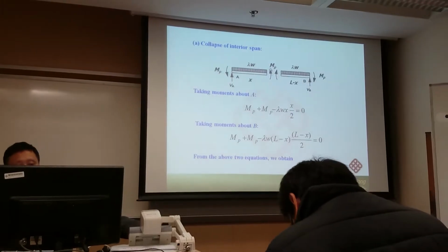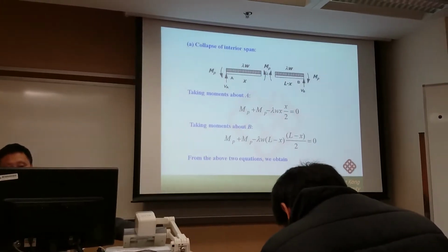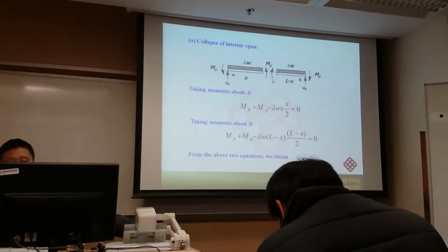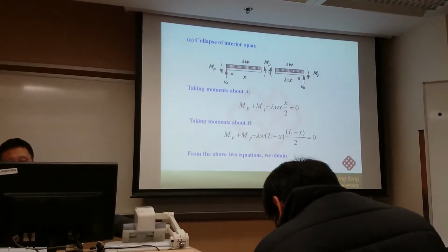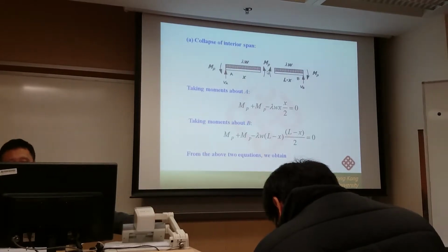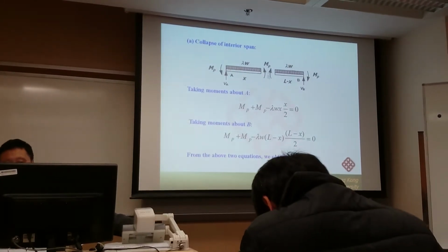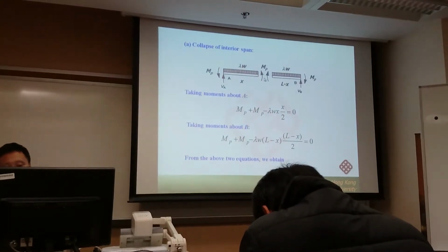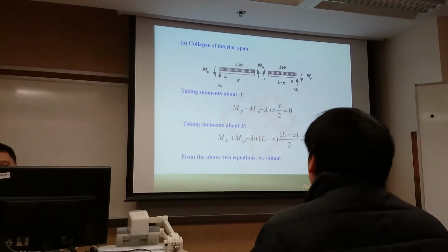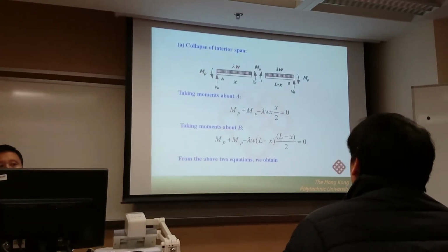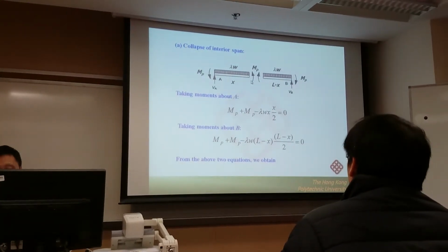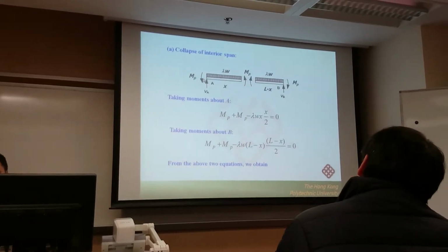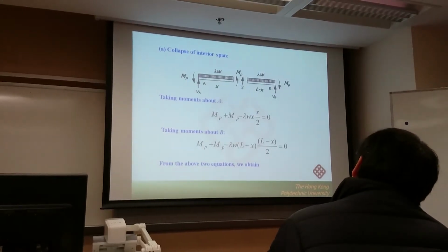So the second moment produces a tension. So this is the direction of the second moment. And also we have a conclusion: the shear force at the plus hinge section is equal to 0. So here the shear force must be equal to 0. Please understand why I didn't show shear force here, because shear force for this section is equal to 0. So this is the reason why I didn't put the shear force here. But at the two ends we should have the shear force.